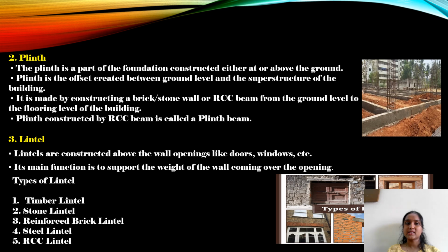Second one is plinth. The plinth is a part of the foundation constructed either at or above the ground. Plinth is the offset created between the ground level and the superstructure of the building. It is made by construction of bricks or stone wall or RCC beam from the ground level to the flooring level of the building. Plinth constructed by RCC beam is called a plinth beam.